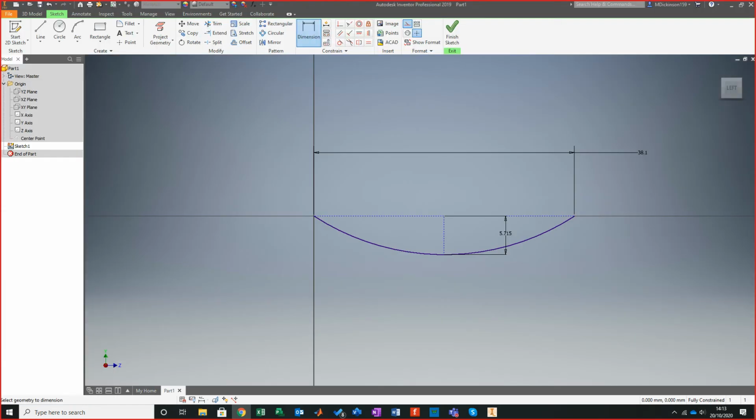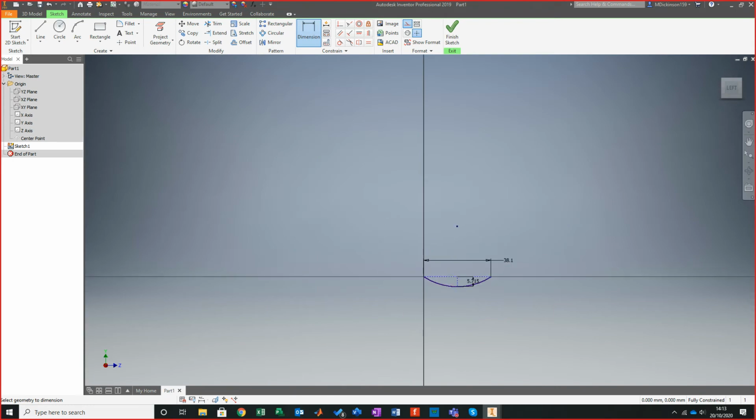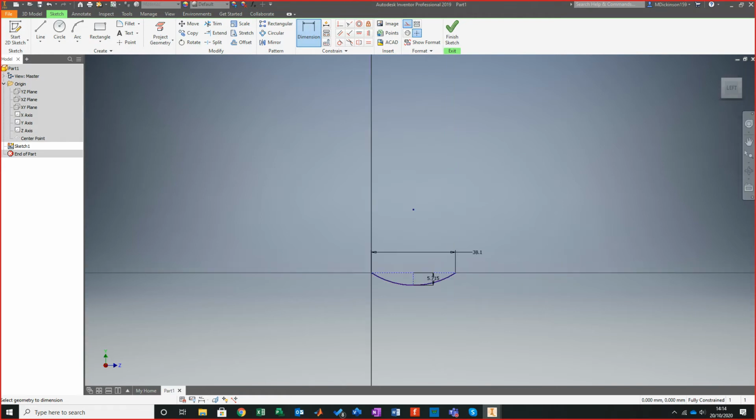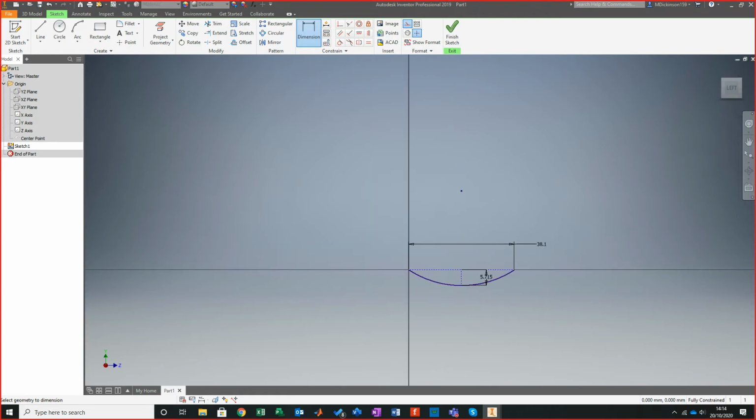So now I want to take the next step. This next step, no matter which CAD system you use, of creating this changeable spline is a bit problematic. Well, it's not problematic, it's temperamental in some ways. It's delicate, so let's say. Now I can either use an interpolation or control vertexes. The way I've presented it on the notes, it is an interpolation method.